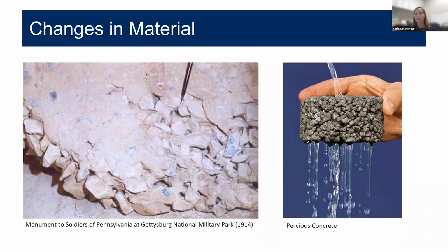And so that led to decreases in water to cement ratio, meaning we had less water convenience, and therefore workability is now achieved by using admixtures. So we're seeing kind of a trend in the different mix designs because of the technology and developments in materials.